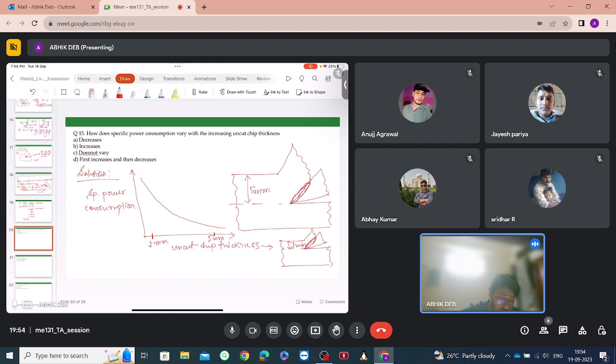Like for one cut, say the frictional work required is Fw. For this one also we require Fw. Therefore, since we need 5 cuts, we need a total frictional work of 5 Fw. So this frictional work will be more.